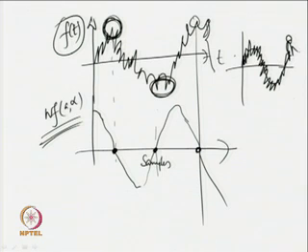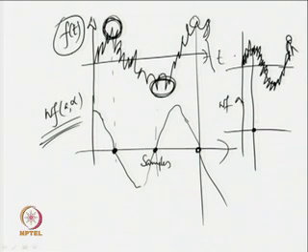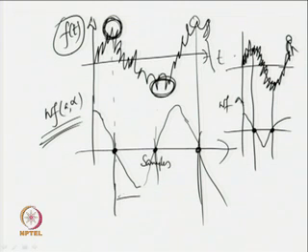Okay. Then the wavelet transform of this one, this is the peak from the clean signal and this is the peak from the clean signal. So, the wavelet transform will be having some value like this. So, you will have a plot like this. So, the peaks have been located correctly. So, from the location of the peaks, basically we do get correct information about the zero crossings of the signal, and from the zero crossings you do get correct information about the period of the signal or ultimately the ultimate frequency of the signal. Okay.